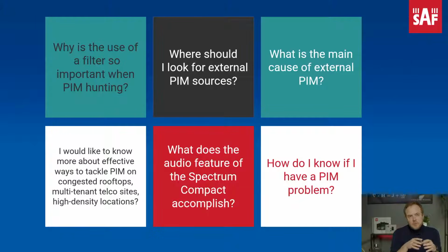This means that when we are looking for PIM sources, we usually work at relatively low signal levels compared to the base station power levels. And if we wouldn't be using a filter, we wouldn't be able to see or detect those relatively low level PIM signals.